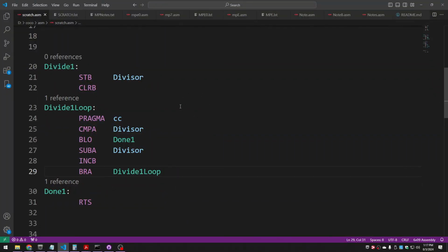The 6809 is the first processor that I learned assembly on a long time ago, and then after I had done a bit of that as a kid, I then moved on to doing some amount of assembly on 68000 and x86. And in particular from x86, I started to get used to certain conveniences, like when I'm comparing two values, I can actually compare one register with another. And then recently, when I returned back to 6809, I found myself surprised: on the 6809 I cannot compare two registers together.